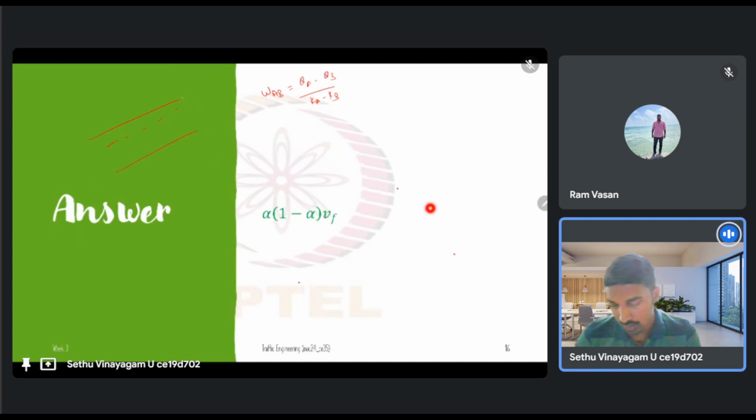We are given that, so let us say this is the location where the two traffic states meet. Okay, so A and B. The traffic state A is some alpha times Kj, and B is 1 minus alpha times Kj, right? So Kj is fixed, right? So for this particular road it is some constant, Kj. And so we have alpha times Kj and 1 minus alpha times Kj, and we also know, or are given, that alpha is less than 0.5, right? So what does it mean? Which means Ka, the traffic density at A, is lesser than the density at B.